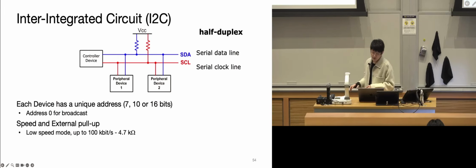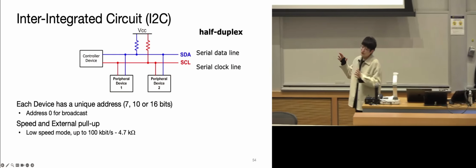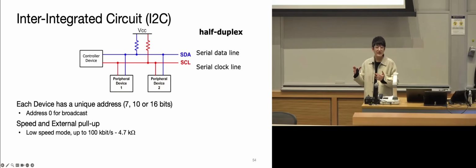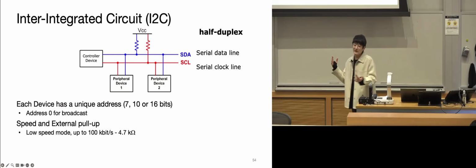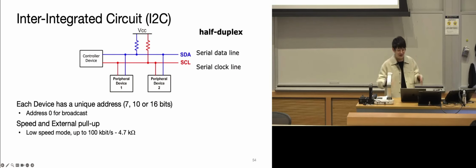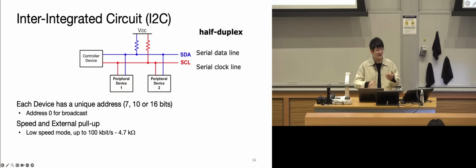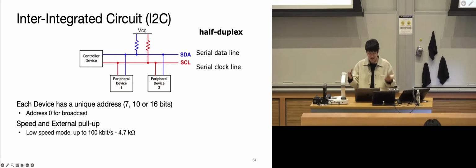When multiple controllers are trying to broadcast on the SDA, whoever gets to 0 wins the SDA bus. It's kind of an odd way to do it, but if you think more about it, it actually works, and it doesn't add any additional lines.